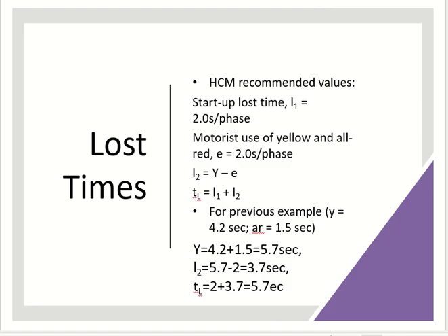And obviously to keep a factor of safety, we are taking the clearance loss time as more than the all red time. The last 1 second of yellow is like the factor of safety, for the extra 2 on the safe side. So this is the difference between them.